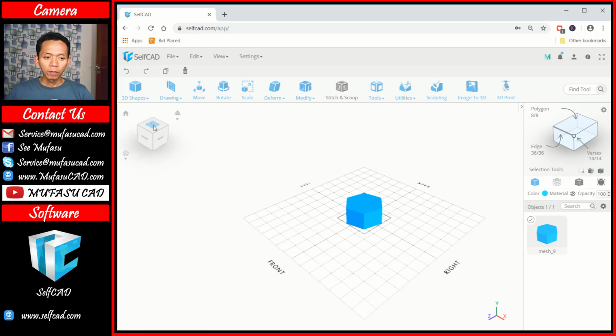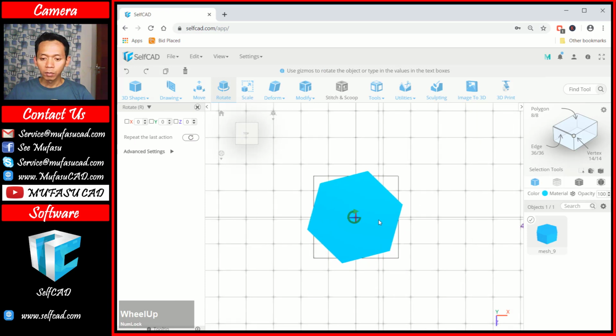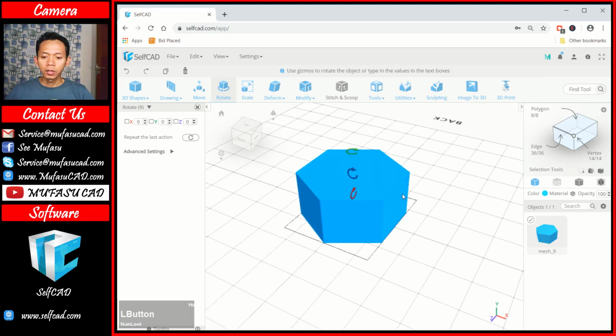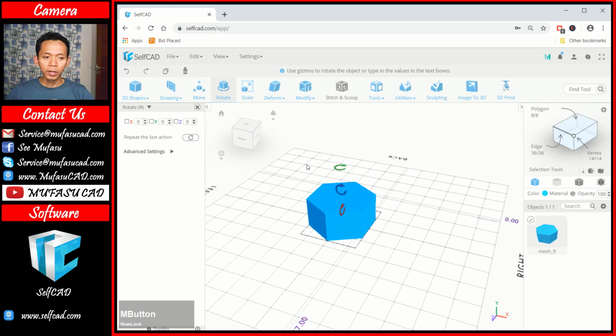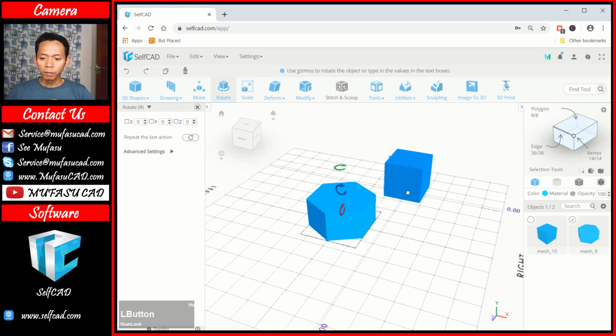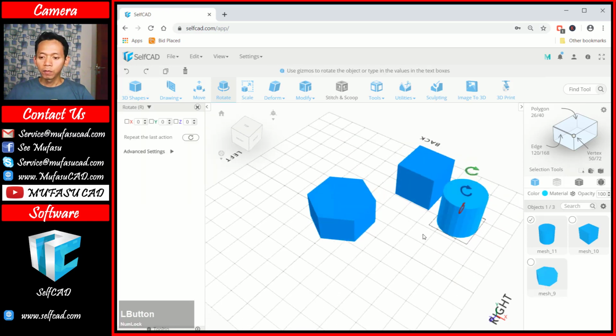I will change to top view, and I will use this rotate command to rotate these 3D models in the green axis, okay, to this point. Next, I will insert new 3D models. We can insert a cube. You can drag and drop it to this point. We insert a cylinder object again at this point. Okay, I will move this cylinder object into this 3D box.